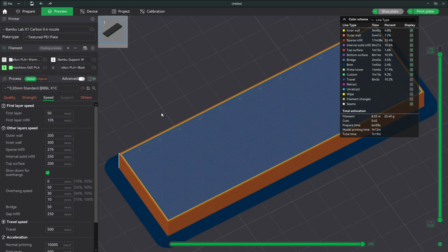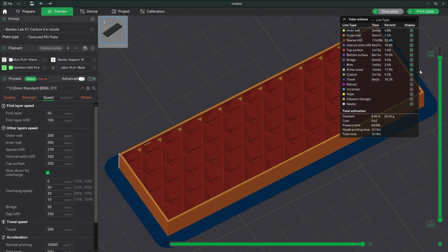And I have printed them at speed before, and they come out just fine. Make sure your infill pattern beneath it is going to give it small gaps to bridge. Print it fast, you're fine. If you start to see pillowing, where it looks like there's tears in that bridging layer, you can turn the speed down a little bit.